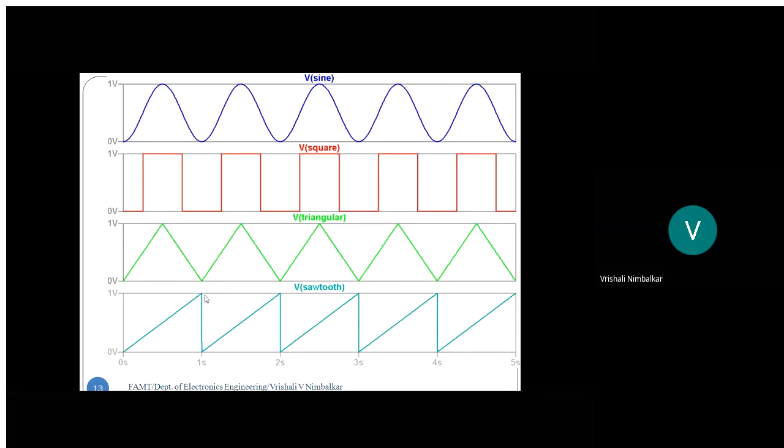In our interfacing diagram, the maximum limit is 10 volt. After FF, if I still increment, the accumulator will be 0 and 0 will be sent. So immediately the next value is 0 volt, and the waveform drops down to 0. Then again I go on sending the digital values 0, 1, 2, 3, 4, 5 up to FF, and after FF, back to 0. That's how we generate a ramp waveform.